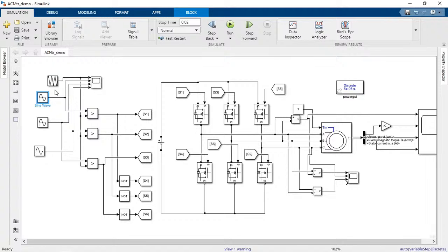We have one more demo. It's called a closed loop. Yeah, so take this simulation. It's the same method. See here, the entire PWM is generated here. With this method, the motor speed is taken as a reference speed. By comparing with the actual speed, we get the error.